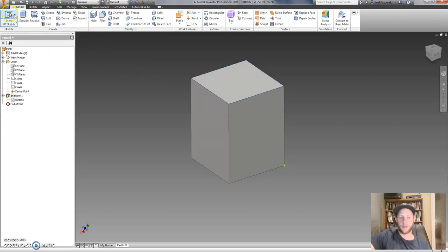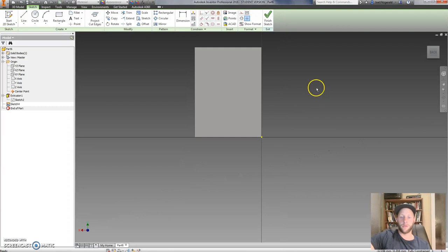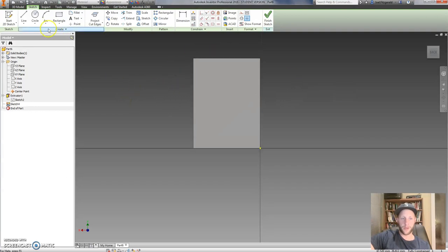So start by clicking sketch, choose the face we want to sketch onto. We're going to choose this face, click, and the screen will rotate us into this. Now, because we've got this existing geometry, or this existing feature, we can sketch onto this. So one thing we can do is build some lines, and you'll notice that I can now click and select the existing geometry.